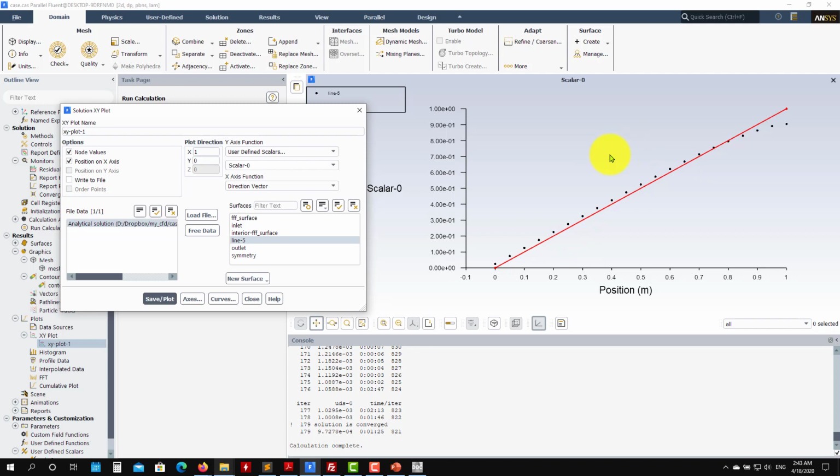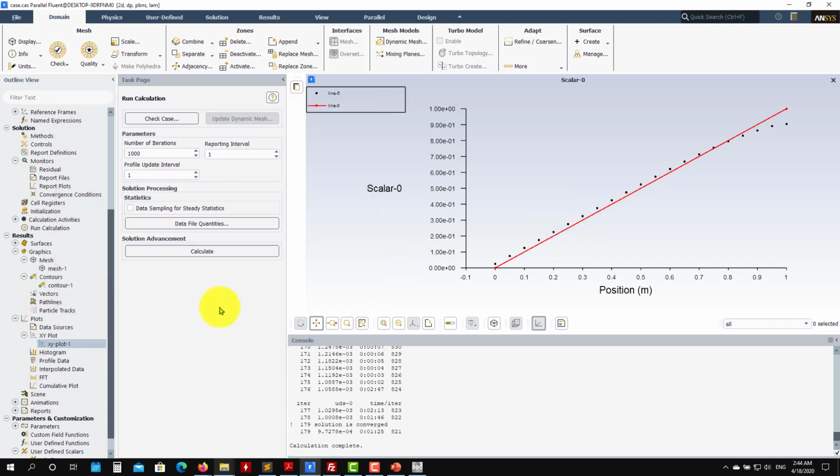In such a simple problem, you see that we have a lot. You can imagine industrial problems. That is why we don't use upwind to get the final solution. But keep in mind that upwind will always give you a solution. For the craziest, most complicated problem, it will give you a solution, but it will add too much error to the final solution. That's why we want second order accurate solutions.